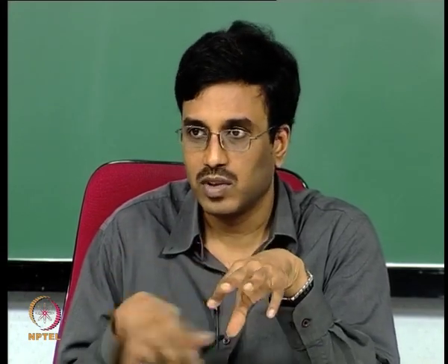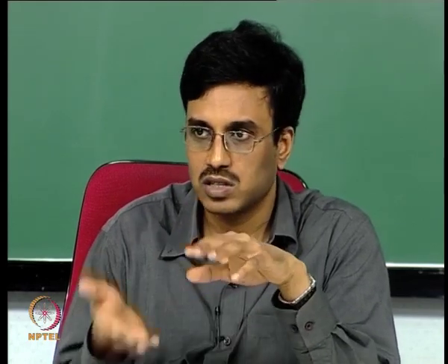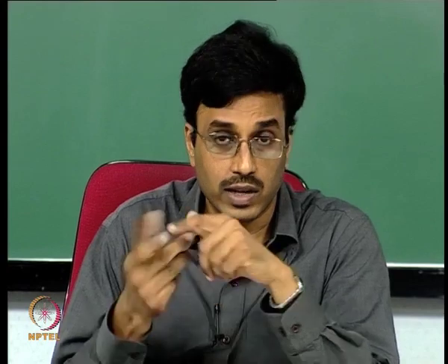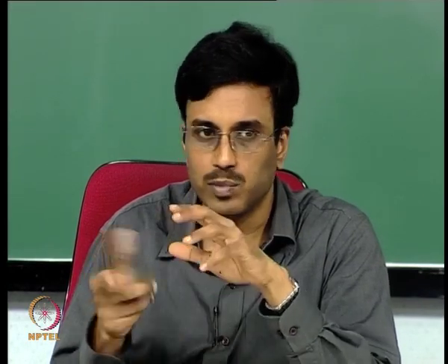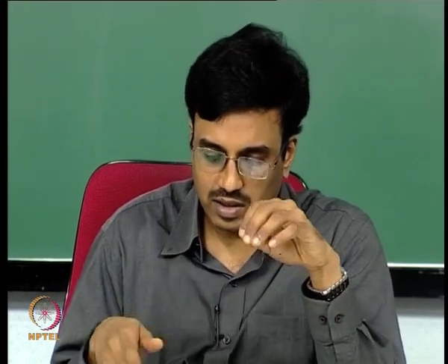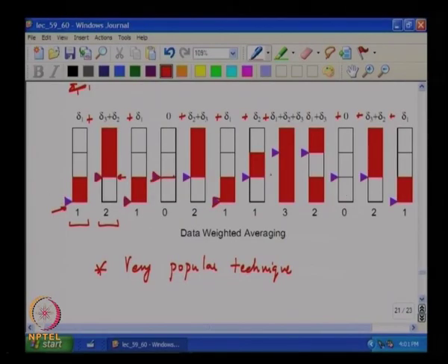So regardless of whatever you do to come up with the final DAC, if it is indeed doing mismatch noise shaping without adding distortion and so on, it will turn out that each one of these thermometer drive waveforms is a linear function of the input plus some shape noise. With DWA you can actually work through this pointer business and show that that is indeed the case. It is a very messy thing, but that is what it is.